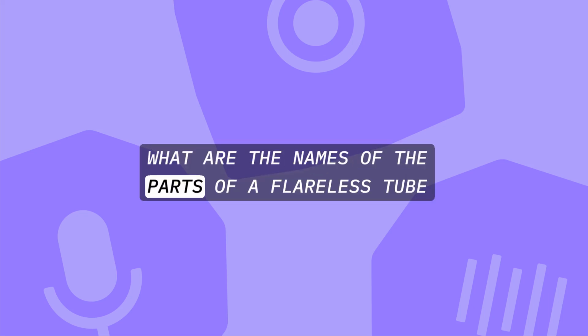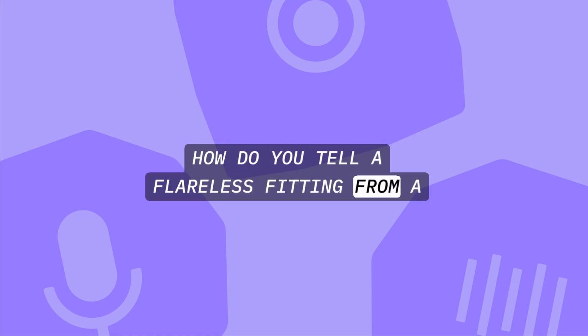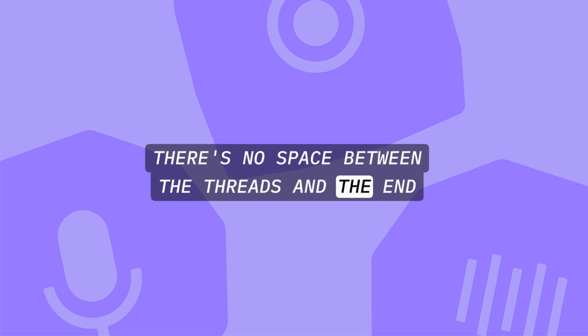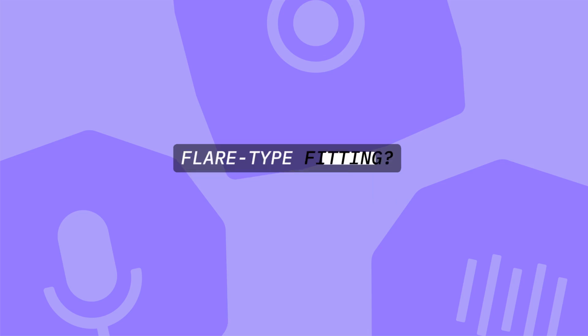What are the names of the parts of a flareless tube fitting? The nut and the ferrule, or sleeve. How do you tell a flareless fitting from a flare type fitting? Flareless fittings do not have a flare cone, and there's no space between the threads and the end of the fitting. What is the effect of over-tightening a flare type fitting?